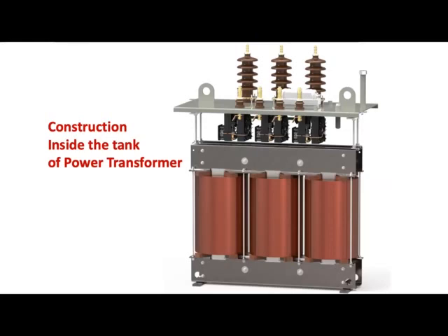Now this is the practical transformer. Again, this is a core type of transformer. As you can see, the core is not at all visible. The limbs are not at all visible. The yokes are visible. But the winding is being placed over here of the transformer. And on the top, what you see, the brown color, and the top of it is the connectors and the bushings. Bushings depend on the voltage level. And the connectors are provided to have an external connection with the transmission system or the distribution system, wherever it is placed, to make electrical connection there.